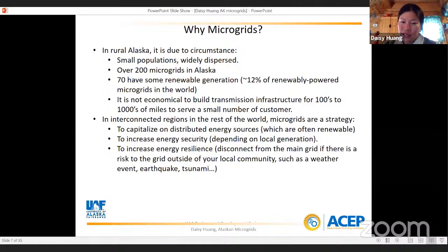And then the final reason, and this is also of interest to the military, they're big on this, is to increase the resilience of your grid. Rolling blackouts have happened in the lower 48. Very famously, a few years ago, one happened all over the Northeast, which is a big deal because that's their big population center. New York was in the dark. But the idea is if you have islanding capability in your different load centers, if you can cut off from the grid, you can save your community from the rolling blackout. If there's an outage in the community down the road, you can cut off and disconnect for a couple of hours, and your community can be more resilient.